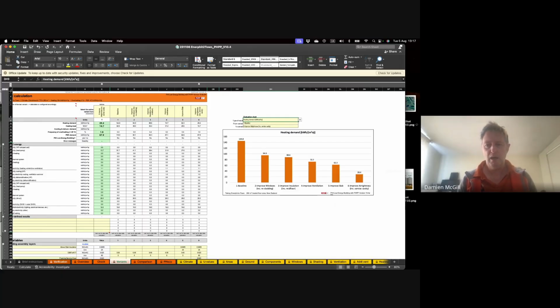But the current code schedule method is R6.6. It's about to get tossed out for a modeling or calculation method, ostensibly to try and save money, not worry about comfort levels. But somewhere in that R6 level of insulation would give you a good grip. All your heat goes out your roof, so to a point, that's where you should start.